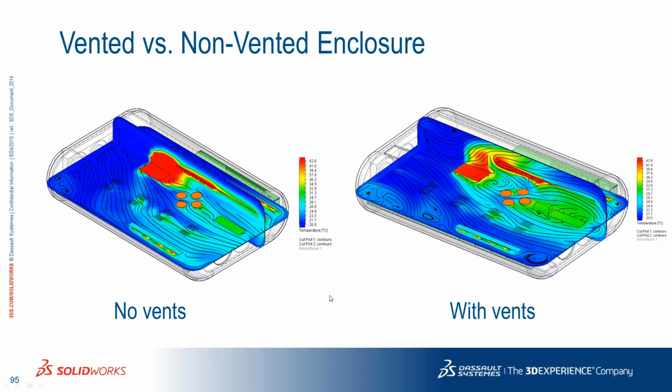I don't want to see these recirculation areas. So that's the value add-on of using flow simulation to test multiple design ideas, to make sure that something that might look or seem logical may not be the case. In this case, putting vents on the top and the bottom might give us the idea that, oh yeah, I'm going to keep the thing much cooler, but it's not really the case here.